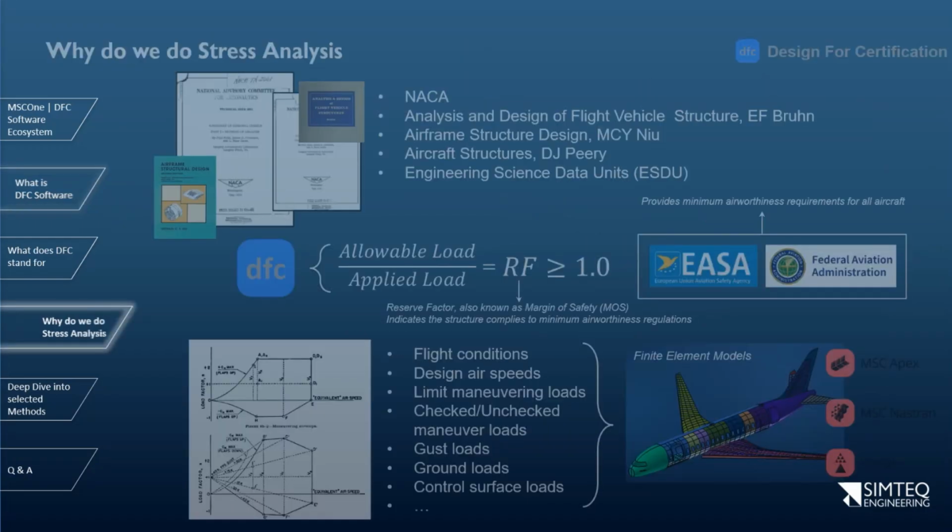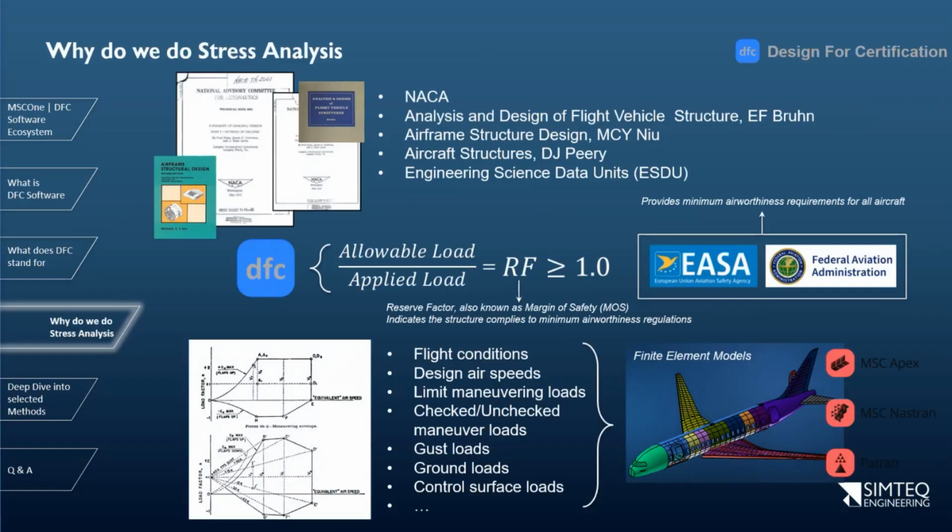Like I say, the details of this are all in the previous session, but just a quick refresher. We ultimately want to get to a calculation where we compare an allowable load that's been given to us by some of the standard stress methods that are out there today, and we want to compare that to an applied load that's being extracted from a finite element model.